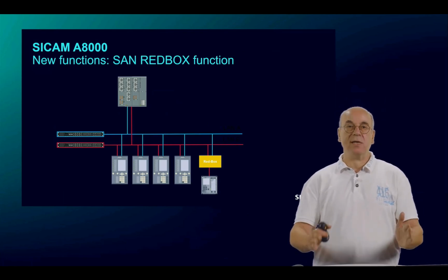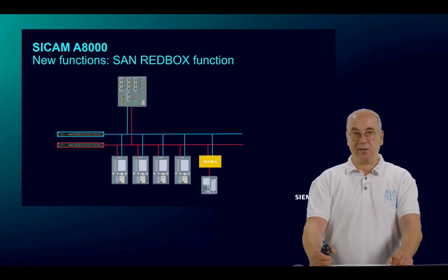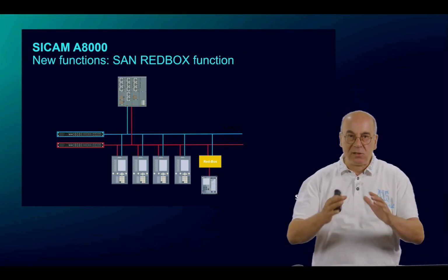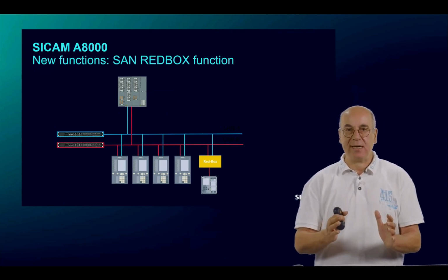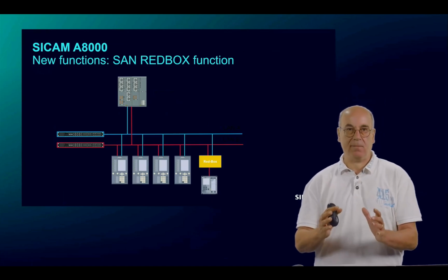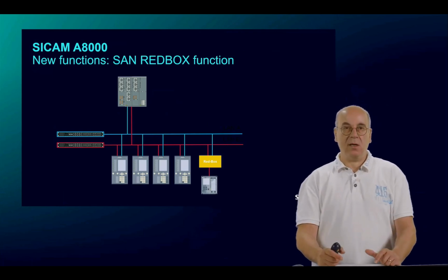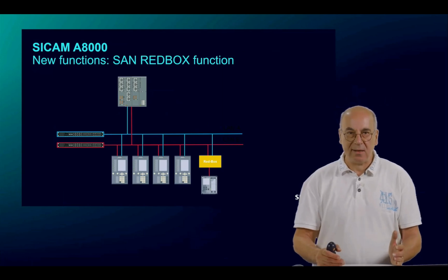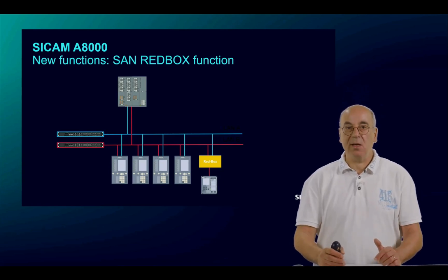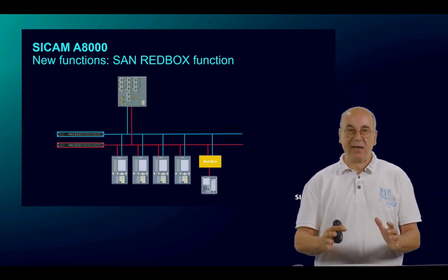That is normally used together with so-called seamless redundancy algorithms like parallel redundancy protocol or high seamless redundancy, where inside of the IED with physical redundant interfaces, a piece of software takes care that no circulating telegrams are blocking the communication and that a double received telegram will be recognized and discarded. IEDs, either with only one physical interface and without this piece of software handling the seamless redundancy, are connected to such networks via a so-called red box, shortly for redundancy box. And this redundancy box provides the physical redundant network interfaces and the piece of software managing the redundancy.